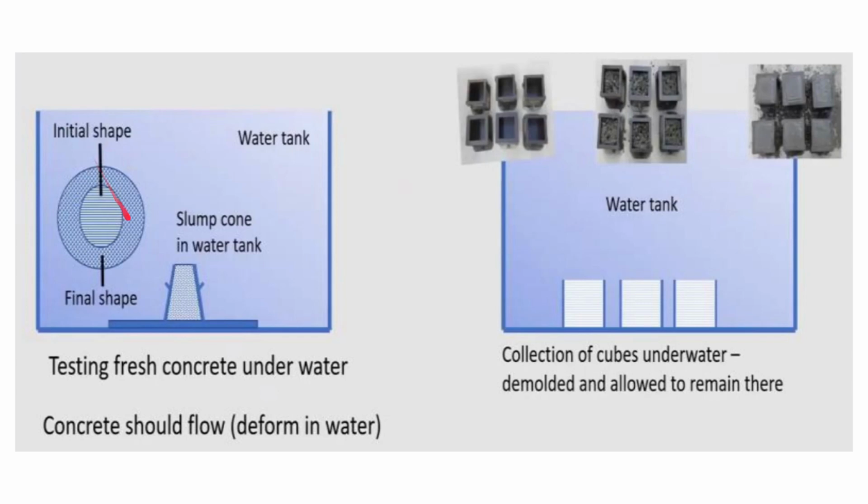After the slump is allowed to flow, this has become the final shape. And you can see here the slump cone in a water tank, and this is filled with water. So, testing fresh concrete underwater: the concrete should flow or deform in water.